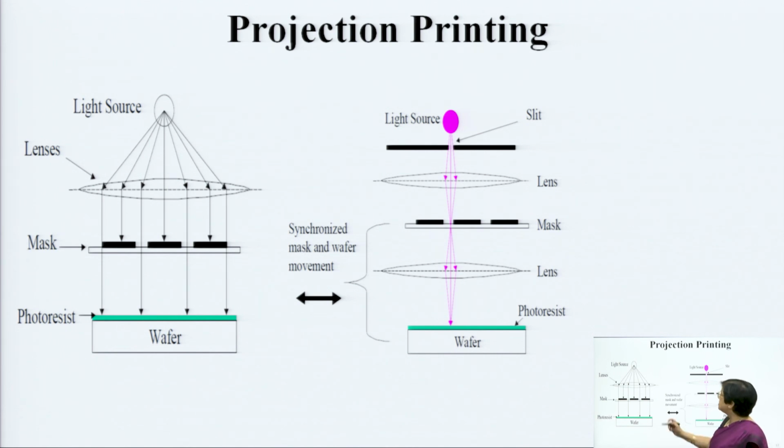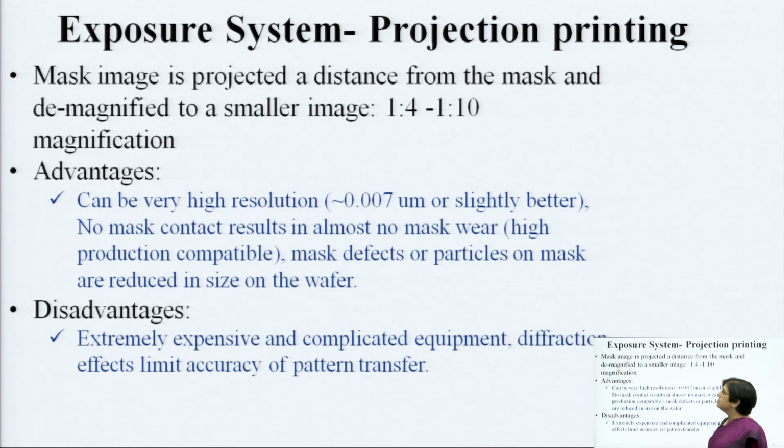Now, with this projection system, you are able to maintain proper distance, and you are able to focus from a distance also. That means degradation of the mask is taken care of, that is, you are protecting the mask life also. Then the system is so precisely developed that there is no shadowing effect and there is no diffraction, everything is precisely controlled. The only drawback is that it is an expensive system.